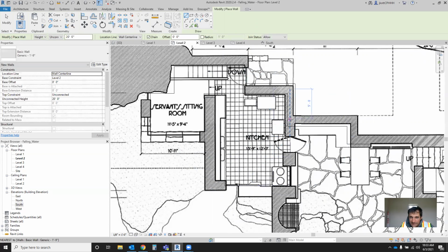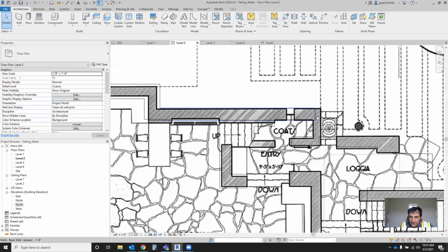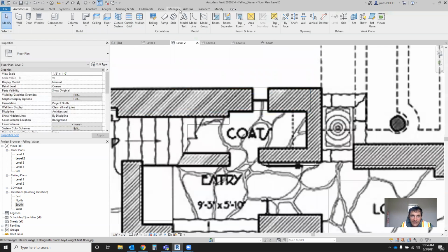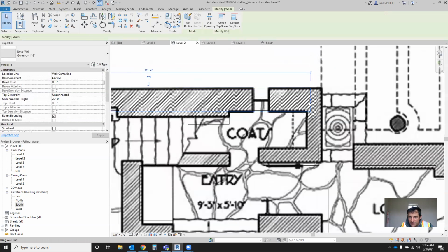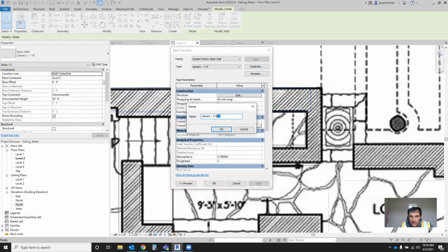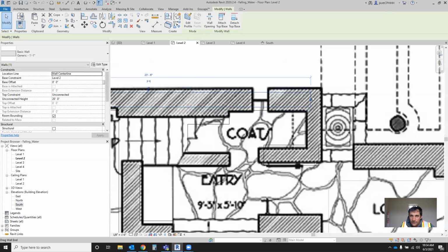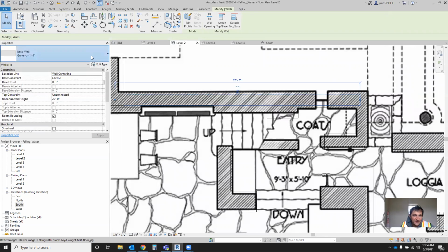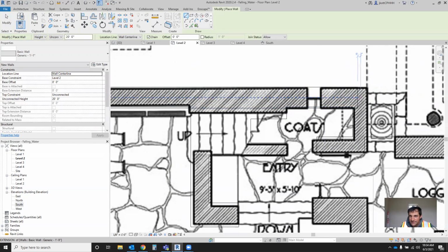Now you're not seeing the wall because we have wireframe turned on. Come to here, come over. Now, you'll notice you start to have different thickness walls. I'd like you to make the walls the correct thickness. So for this wall, you'll measure it, modify, adjust. This is a 1'1" wall. So you'll make a separate wall type, edit, duplicate, and we'll rename this 1'1". We'll edit the thickness to be 1'1", and press OK. Now, we adjusted this wall. We didn't mean to, though. We still want this one to be 1'9". We want to start drawing a new wall that is our 1'1" interior wall now.